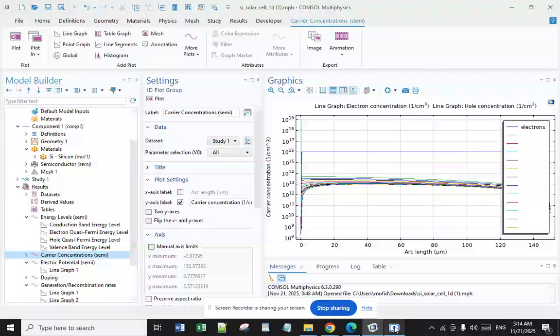And what about advanced designs? Back contact cells place both the front and rear contacts on the rear to eliminate shading. And what about the front contact design placement? The positive contact is a grid on the front surface and the negative contact is a full surface layer on the back. And we want to talk about the pros and cons.